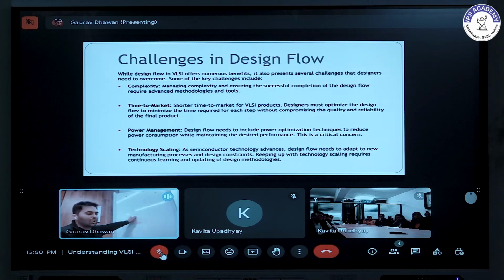When you apply a high voltage, electrons are attracted and form a channel, and you can have current flowing through it, and there is an intensity of field. Now if you reduce this size, some electrons are already there. So without requiring this input, your channel is already there, and current will start flowing. That is what we call leakage current.